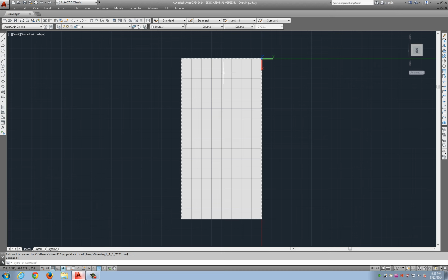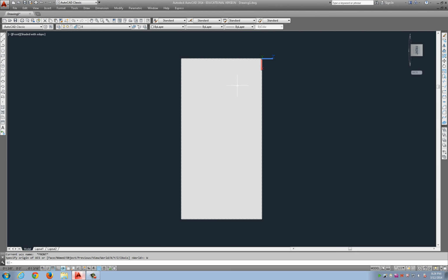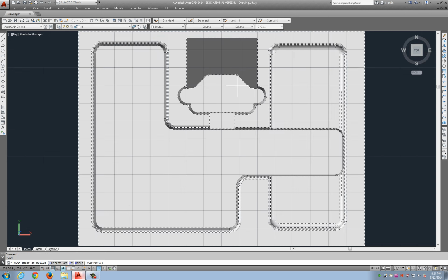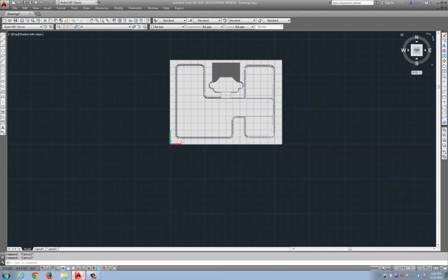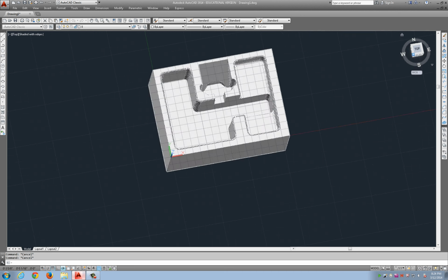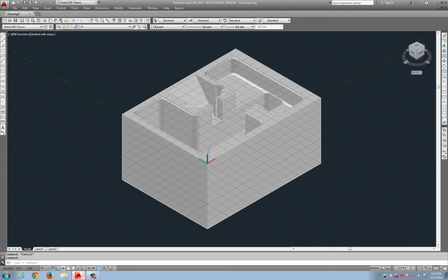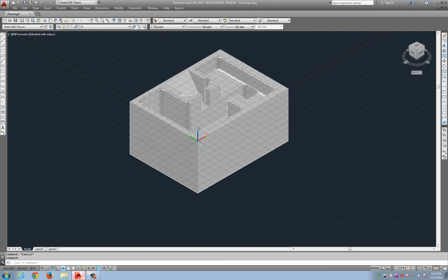Now, this is a confusing way of working. A lot of people work this way in 3D, especially if they're not from original AutoCAD. I'm going to go to UCS World, type in plan, enter, just to get to the plan view. I'm going to show you how to flip up the UCS in a 3D view. If I type in UCS, that activates a bunch of commands.